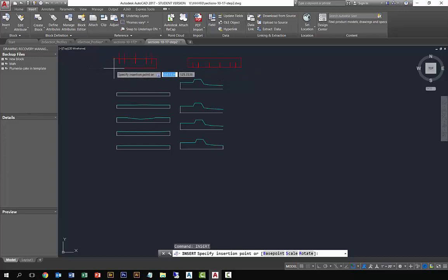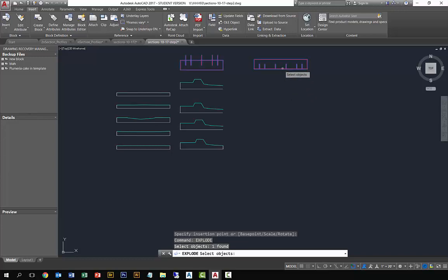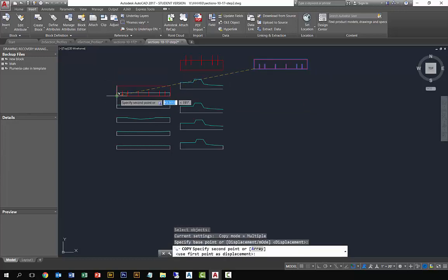At that grid interval, which is 33, 33, 66, 66, 33, 33, or 3 66s for the longitudinal. Now, they're in inch, so you have to explode them so that you can take advantage of it. Because what you're going to do is they're closed polylines, and you're going to snap it to the origin of the corresponding section.